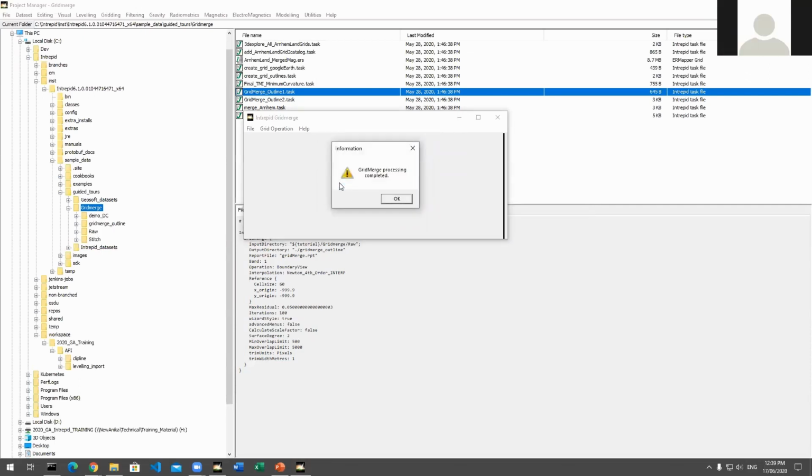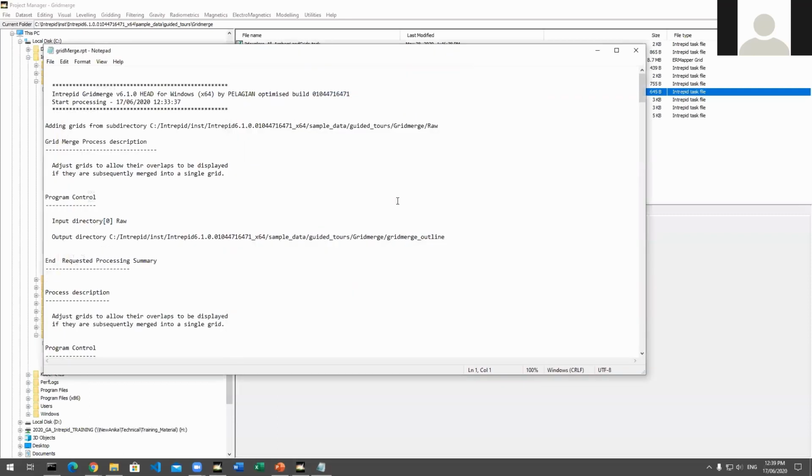What do you do if you only have 2 grids you want to merge? Do you have the base grid as the low ranking grid as well? The base grid doesn't have to be either the high ranking or the low ranking. It's just the level that you wish to bring everything to. So your base grid could be your low ranking, or it could be your high ranking. If you only specify one as the high ranking, inherently the next one becomes low ranking anyway.